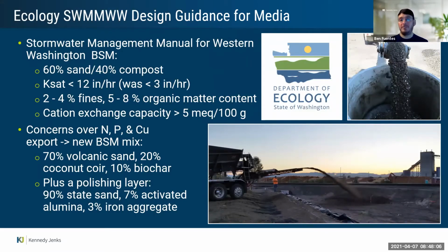So biofiltration has been around for forever, pretty much. It's a very common application for treating stormwater, and Ecology in Washington has provided guidance for a while. The most recent is still, I believe, the 60% sand, 40% compost guidance for 12 inches per hour infiltration rates.